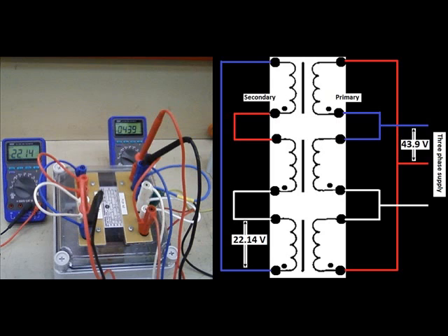Now you'll notice that when we went back, we had a much lower voltage on the first configuration because we had a star primary, so the phase voltage was actually lower. Now that we've connected the delta on the primary, we've got a higher voltage on the actual phase winding itself. So we've now got 44 volts across each phase winding, hence the higher secondary voltage. Again, we only have the one voltage on each side, as the line and the phase voltages are equal for a delta. So 44 volts stepping down to 22 volts.